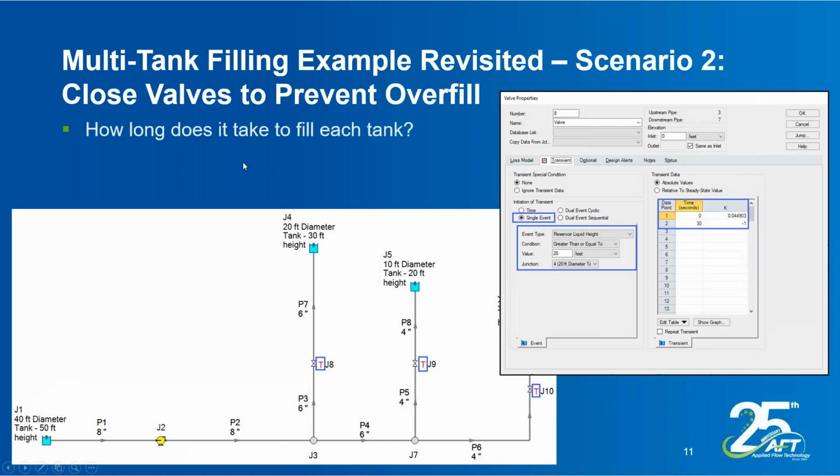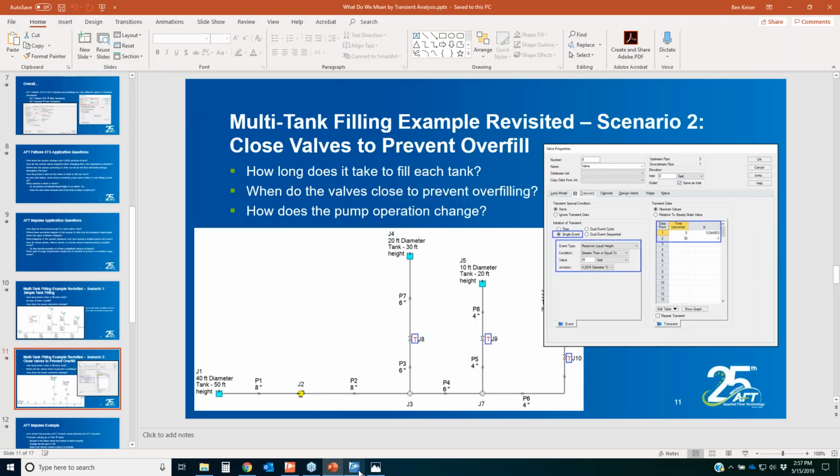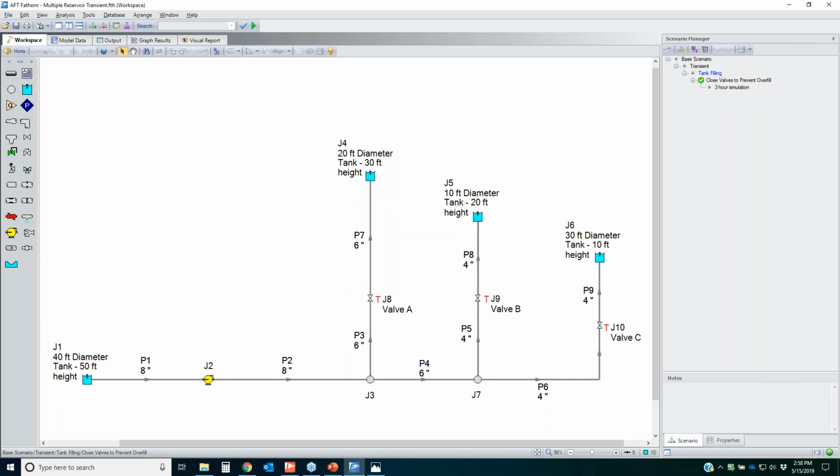So the questions here: how long does it take to fill each tank? When do the valves close to prevent overfilling? How does the pump operation change? So time to jump back into Fathom. This is scenario number 2. Close the valves to prevent overfilling the tank.